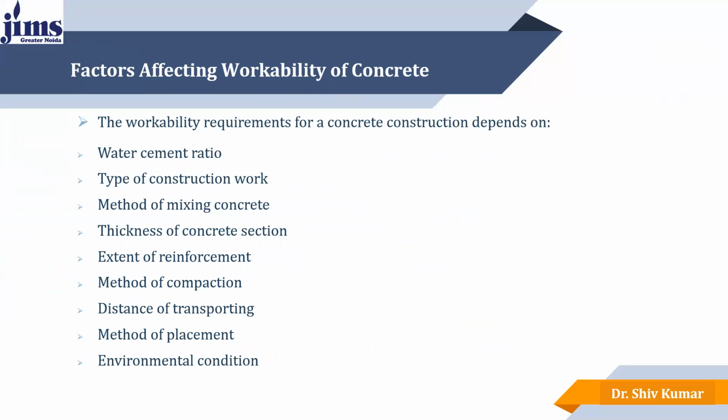Now let's talk about the other factors which affect the workability of concrete. There are so many factors mentioned in the PPT, like the type of construction work, the method of mixing concrete, whether it is manually hand mixed or mechanically mixed, the thickness of the concrete section, the content and extent of reinforcement, the method of compaction, the distance of transportation, the method of placement, and environmental conditions. These are the basic factors that affect the workability a lot.